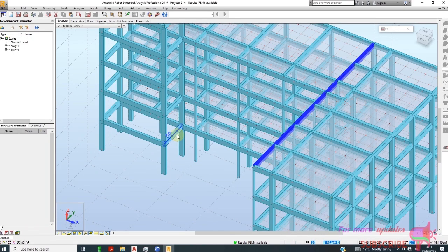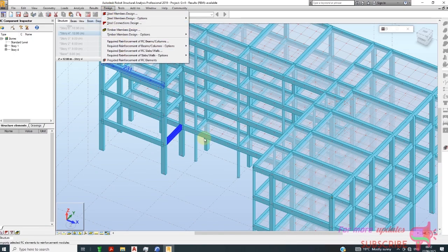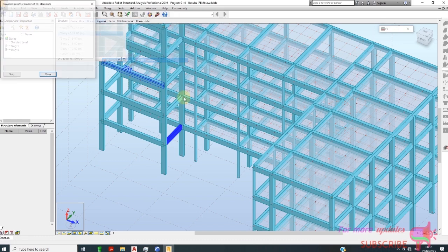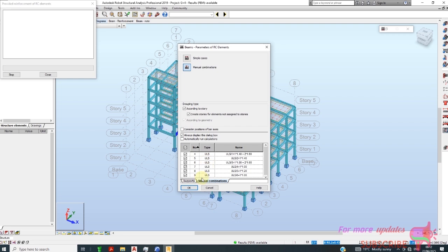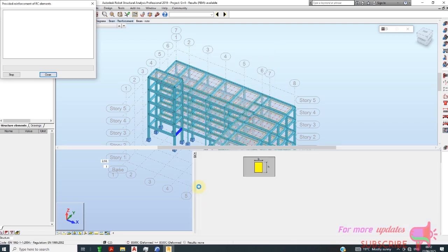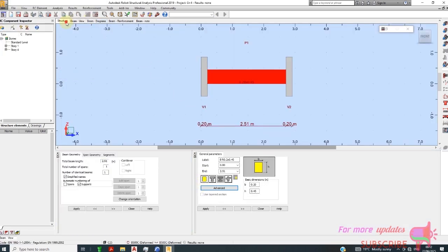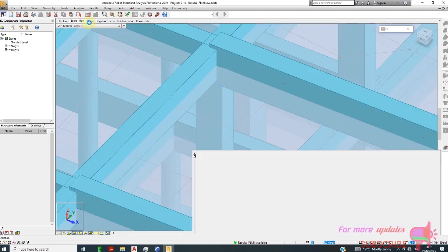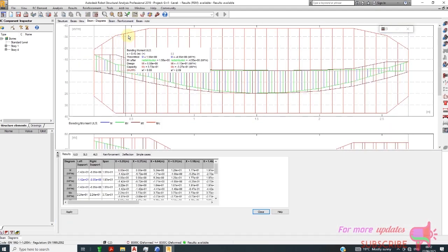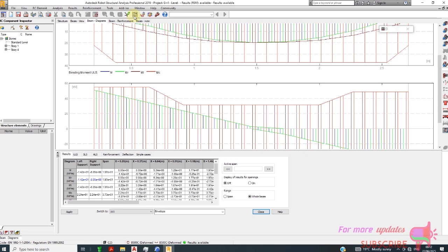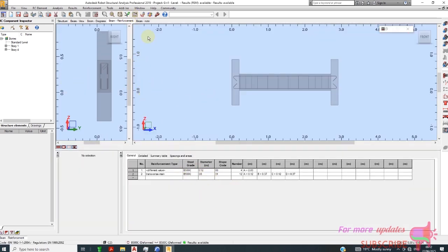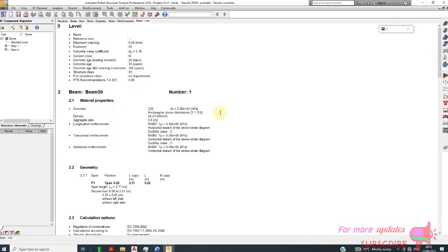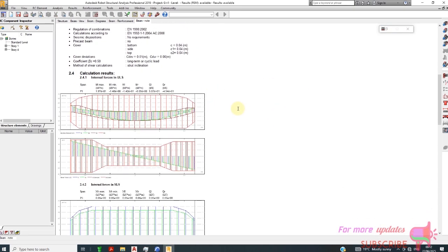Maybe you can check the staircase area where we're having the staircase load. Provide reinforcement. I think also there, the span is too small, so it is okay. Now when it comes to columns, you need to be careful. This is the diagram and reinforcement, the reinforcement required, and then the beam nodes.